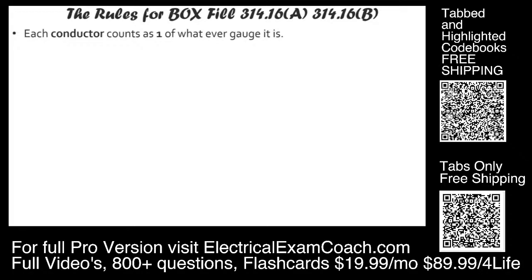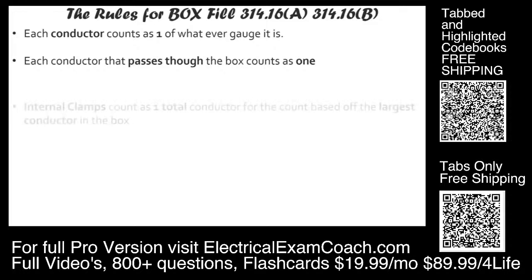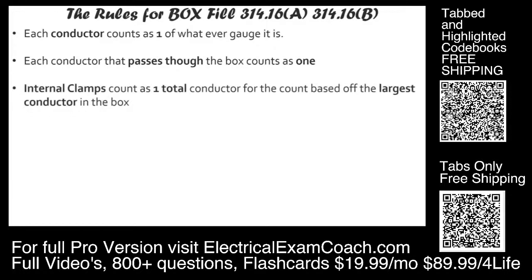So each 12 counts as one, each 10 counts as one, whatever gauge wire it is. Each conductor that passes through the box counts as one. So even if it doesn't terminate or splice inside that box, if it's passing through that box, it counts as one each. Each internal clamp only counts as one total based off the largest conductor that's in the box.